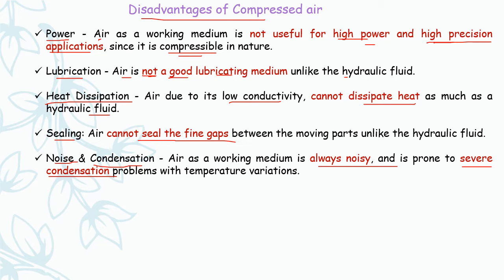And regarding lubrication, air is not a good lubricating medium when you compare it with hydraulic fluids, which act as good lubricating agents. So heat dissipation: because of low conductivity of air, heat dissipation in case of pneumatic systems is lower when you compare it with hydraulic systems.